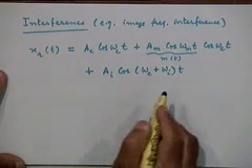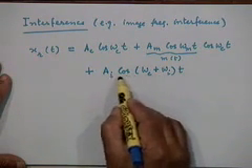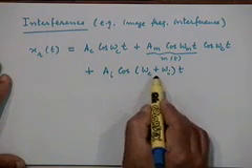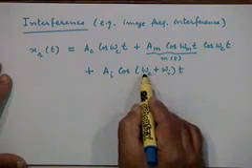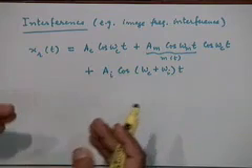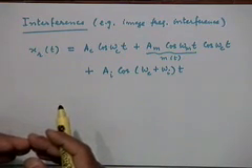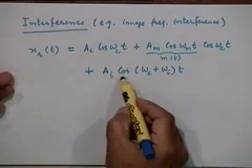Okay, that is a pure tone, a cosine wave of frequency omega_c plus omega_I, where omega_I is close to omega_c and is therefore not rejected either by the RF filter or by the IF filter. So there is this interference present